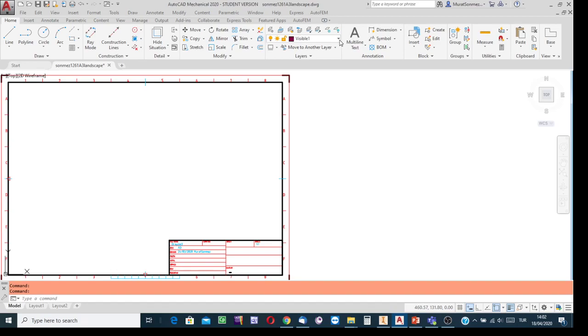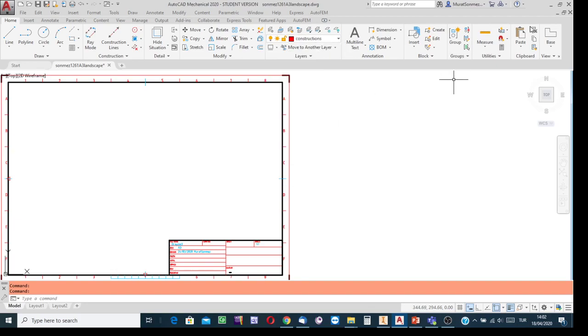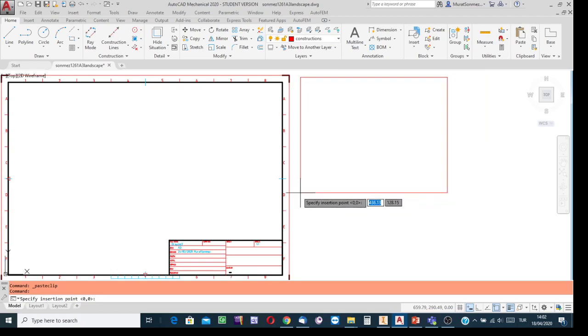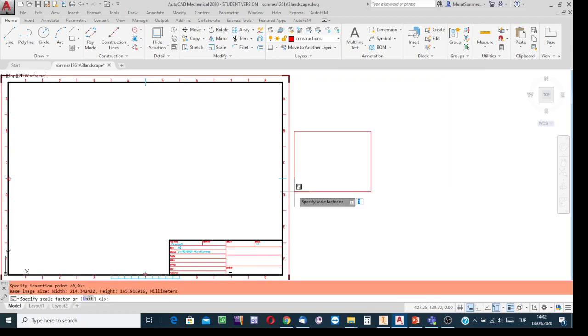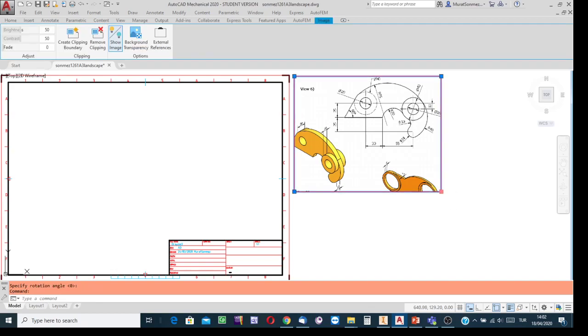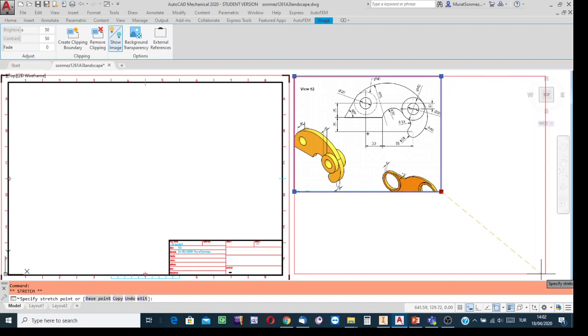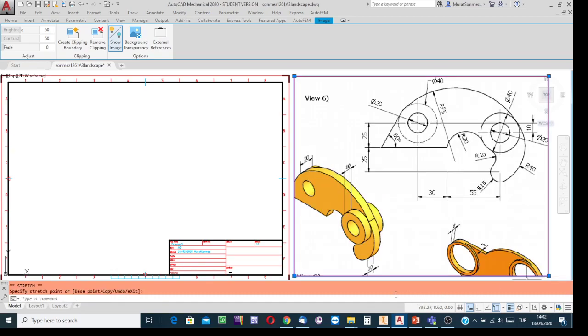Okay, I'm going to paste that screenshot in one of the layers. Which one? I drop the list of the layers, and then why not select construction layer, and then click on paste button. The simulated one is the frame of that screenshot. Click and press enter key twice. Okay, after the anchoring stage, if still you have empty space, make a click at the corner, hold this gripping point and drag the mouse. It is to make the screenshot larger. For your convenience, make it in a suitable size.